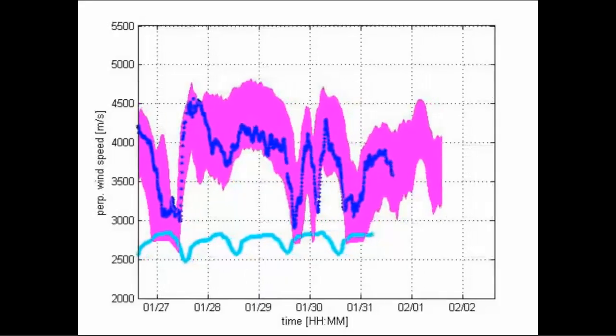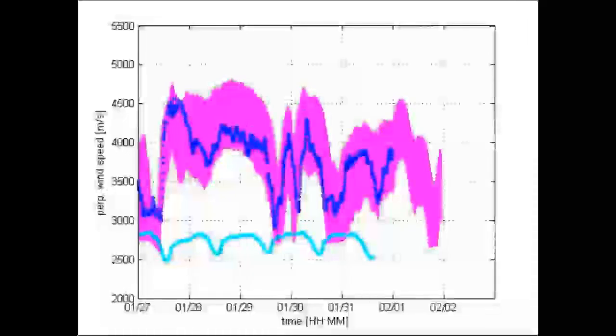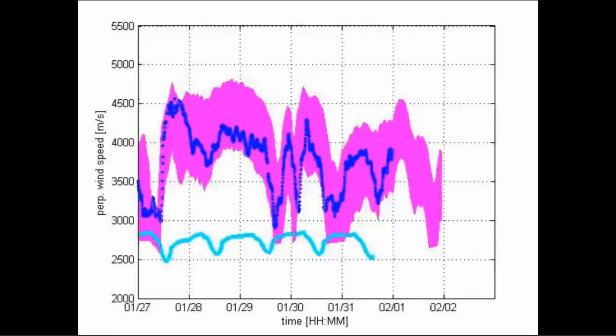Yeah, I think it's clear enough. Rena, if you want to continue. Yes. Only thing to add here, just to make sure everybody is on the same page, that the vertical axis, which says perpendicular wind speed, that's actually wrong in the video. That should obviously be the line rating in amps. And also the forecasting method: the linear regression that you mentioned is for the short-term forecast. The day-ahead forecast and the 2-day-ahead forecast also take into consideration weather forecast information, and have a learning algorithm to improve over time.